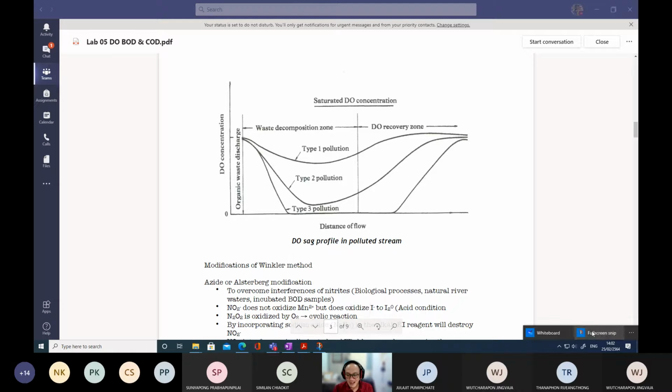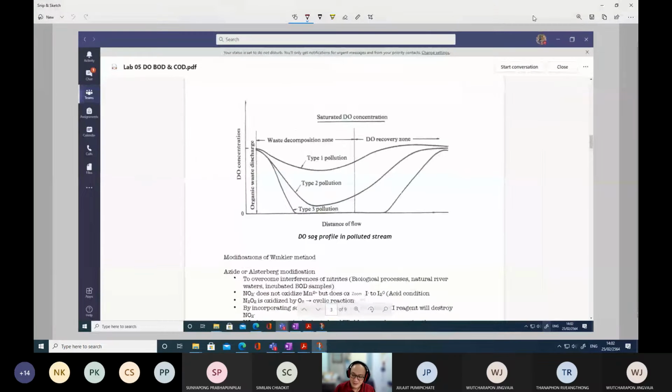This phenomenon we normally call eutrophication. There is the algal bloom, so you see the entire pond will turn green. This is due to the extra amount of algae growing in that pond. This problem arises due to contamination of nitrogen and phosphorus from domestic waste. Nitrogen and phosphorus are normally considered nutrients, so they can enhance the growth of the algae.